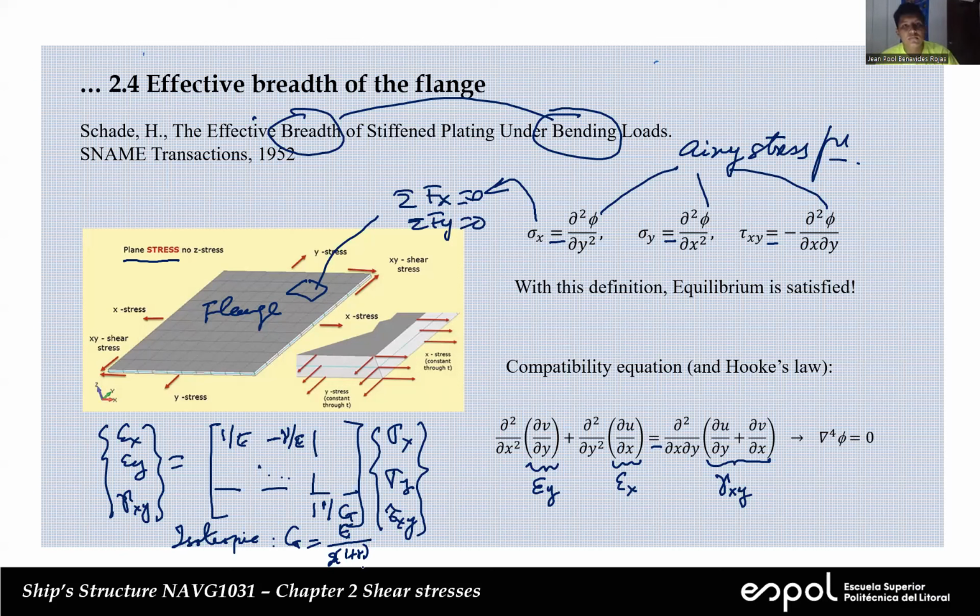Poisson ratio, yes. So when you pull something, it elongates in the x direction, but it reduces its length, its thickness, in the y and z directions. You calculate that using the Poisson ratio. The contrary is also true. If you push, you will compress something, and it will expand in the y and z directions.